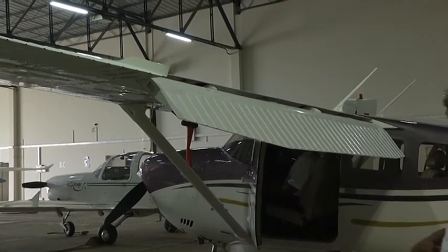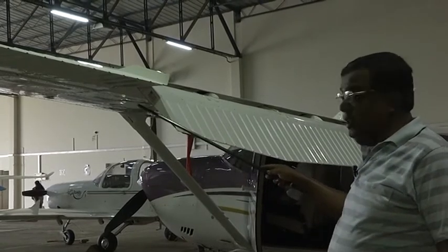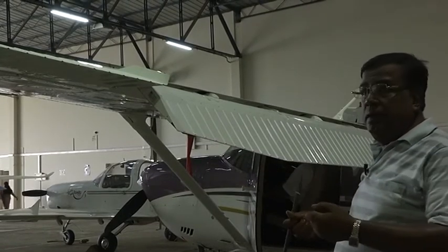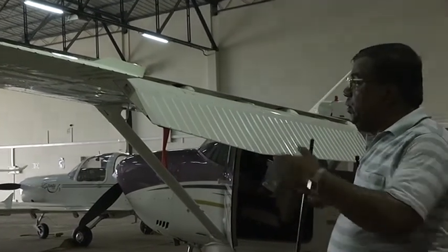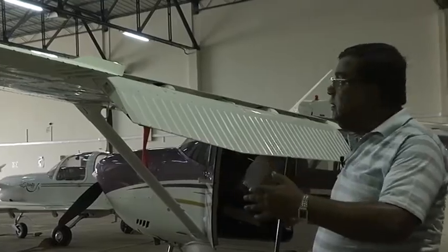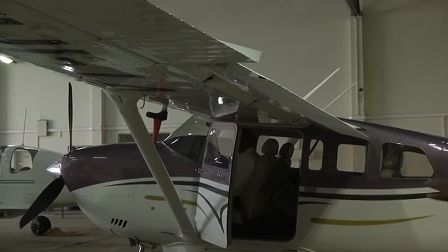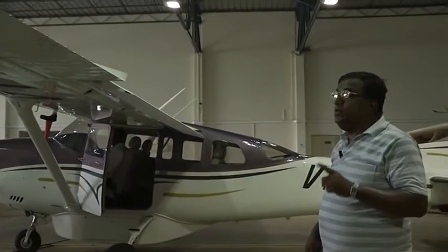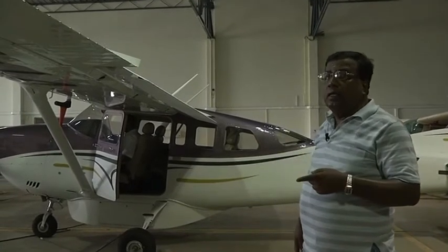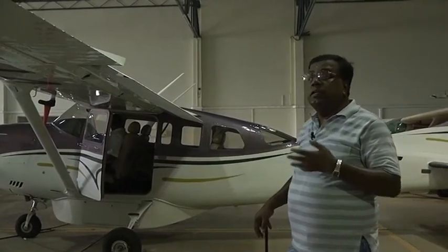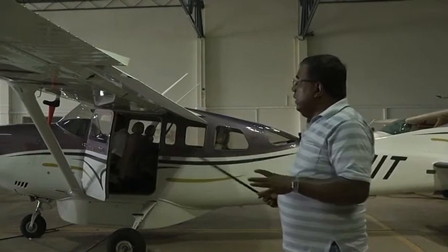And it's very evident now, during landing, when you are putting 40 degrees, primarily we are trying to increase the drag. That helps in braking the airplane to a shorter distance, because it is also important that we have a shorter touchdown distance, right? Please understand, when I say by putting the flaps down we are increasing the lift, but that is at the cost of drag. So that is why in takeoff we have to put a lot of throttle, almost power on. And the CL by CD max reduces, right? Okay? So this is the primary function of a flap.